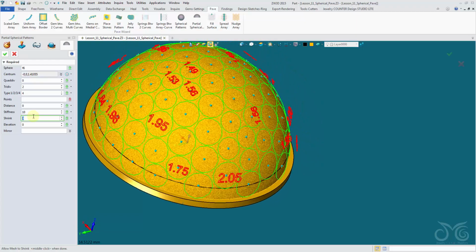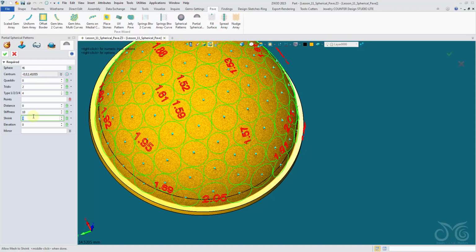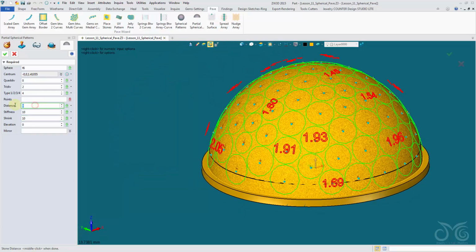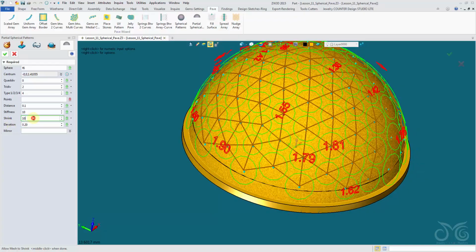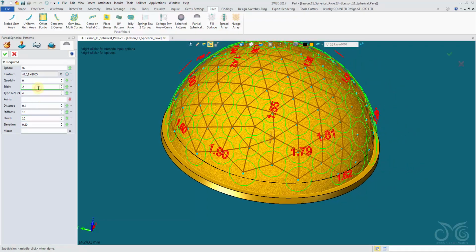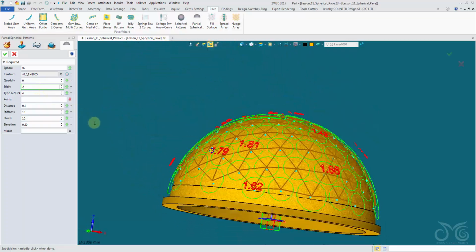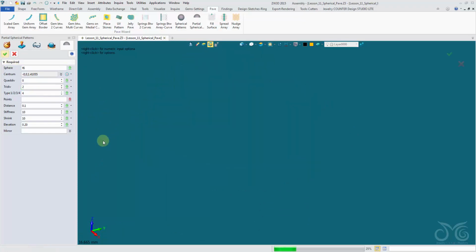Okay, this shrink will tighten up our pave. Increasing the shrink will tighten it up. Here we can increase the distance between our stones. It's at 0.1. Let's give them an elevation. And you just continue until you see the pattern that you like. Confirm the operation.